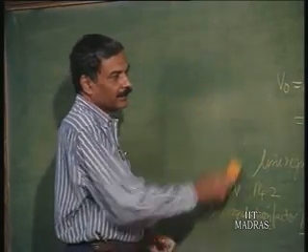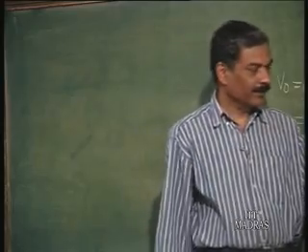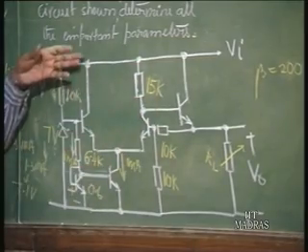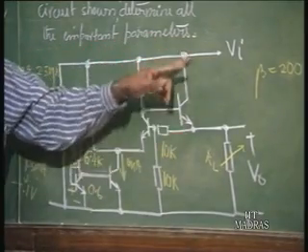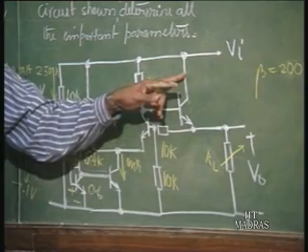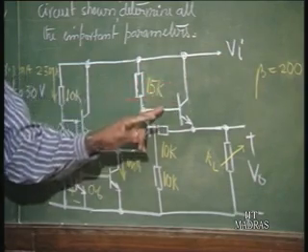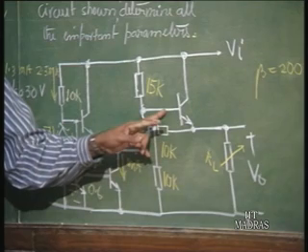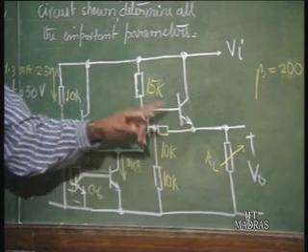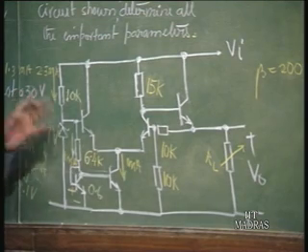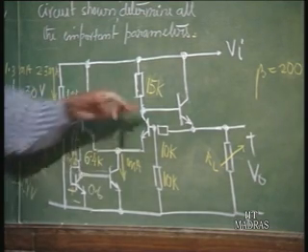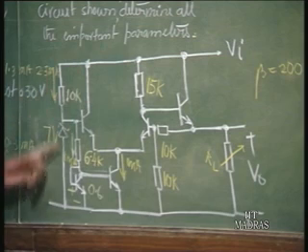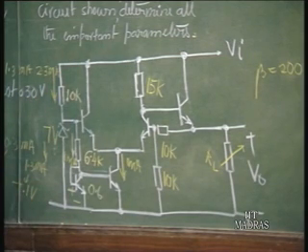So, please understand this is one way, because of line voltage variation output voltage can vary directly. The other way is also through the link here, because this is not a truly very high impedance point, there is a reverse bias junction here, then it is connecting. So, if the reverse bias impedance is not too high, then there will be transmission on this side also. So, all these factors will come into the picture, but the primary factor in this circuit, I told you, because compared to this impedance, this is very low, and therefore, most of the transmission occurs through this path, right. Next,